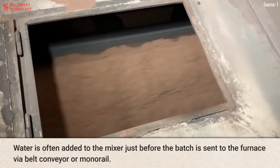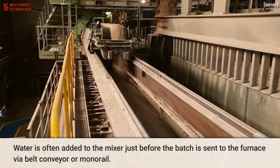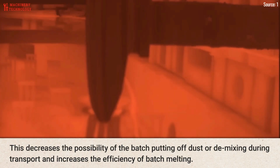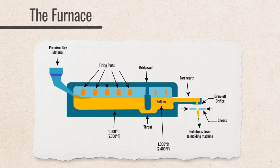Water is often added to the mixer just before the batch is sent to the furnace via belt conveyor or monorail. This decreases the possibility of the batch putting off dust or demixing during transport and increases the efficiency of batch melting. Next is the furnace.